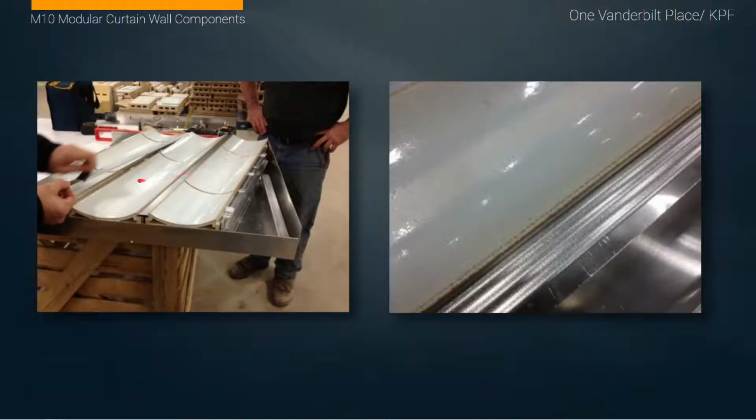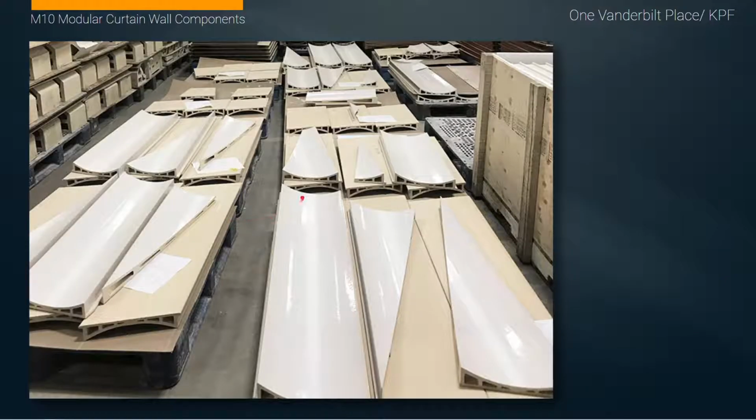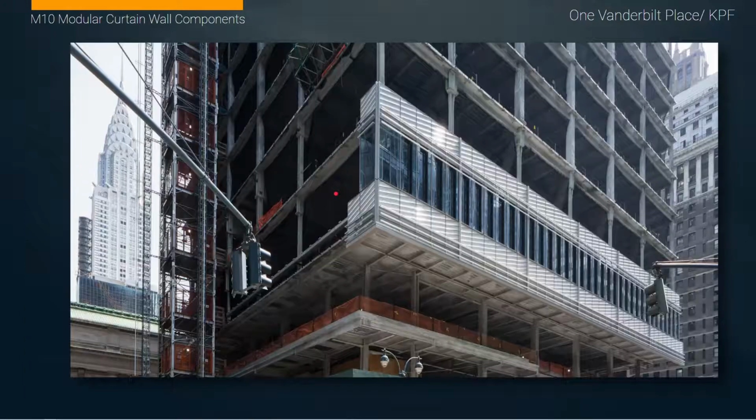So you can see where we only have one little hole on both sides of the panel here. Now when they're full size, we've got these much larger openings. So this ribbing in the panel is intended to reduce the weight of the terracotta. So the terracotta is a hollowed out extruded material, and the hollows reduce the weight of the terracotta. Okay, so back to our project.